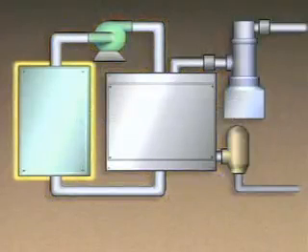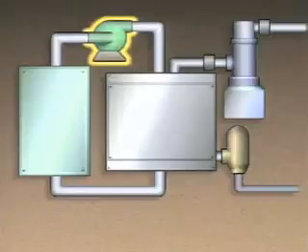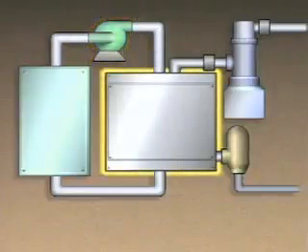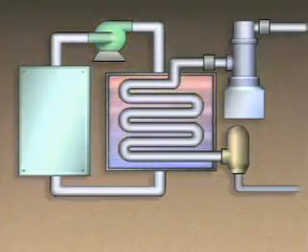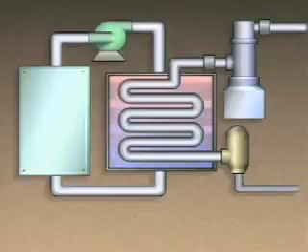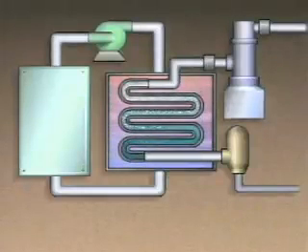The brine flows through the process equipment where it absorbs heat and cools the equipment. A pump is used to create flow through the brine cooling system. The brine is then pumped to a heat exchanger. The heat exchanger in the brine cooling system is the evaporator in the refrigeration system. In the evaporator, the brine acts as the heat source, and its heat is absorbed by the refrigerant.